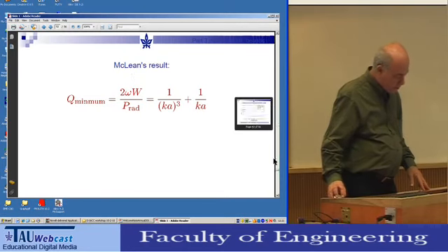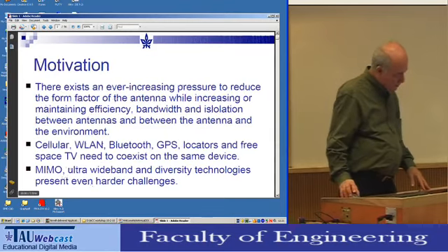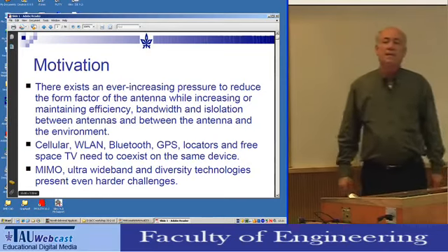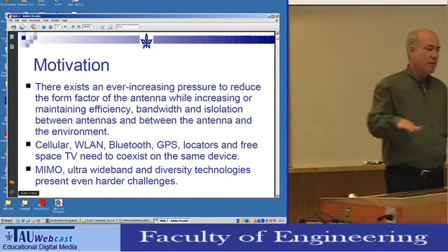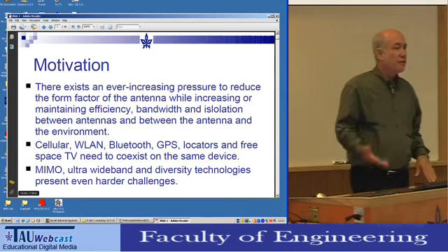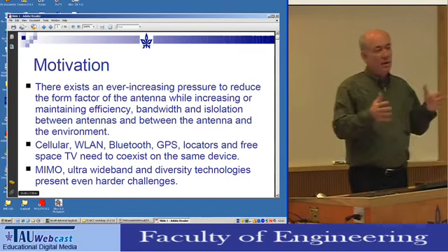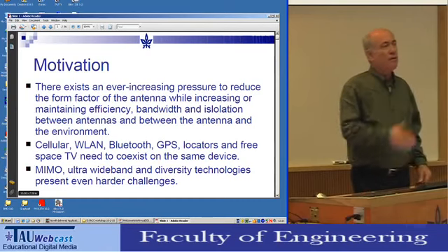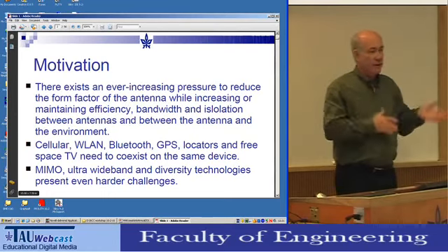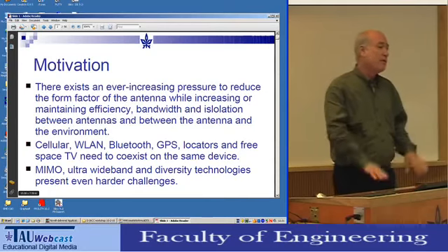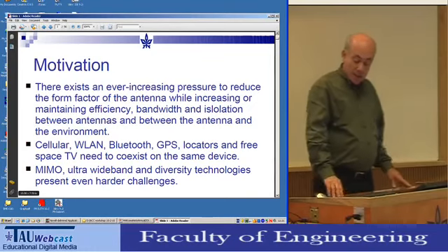Let's see. We were talking about MIMO. I was trying to mention that too at the beginning. MIMO is different than just an array. Everything I was saying in this presentation was about working at the same frequency range. Of course, if you work at different frequencies, that's fine. But if you want to accumulate signals at the same frequency from different directions, different polarizations, and so on, for diversity, then everything applies. But if it's different frequencies, then... same frequency, but different signals in each antenna. That's the MIMO. Well, then the problem is there.